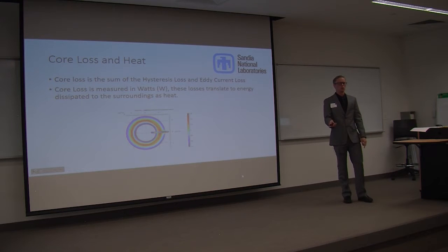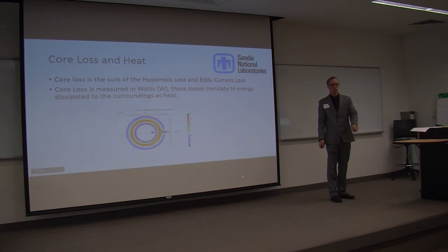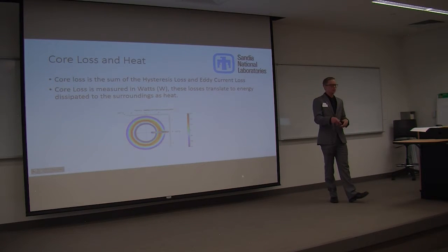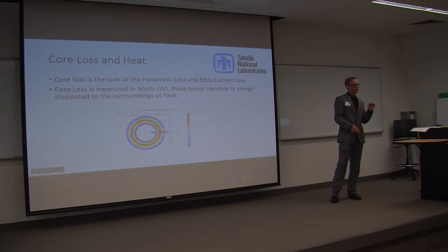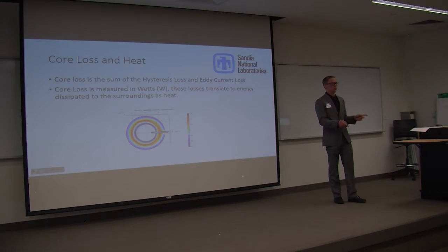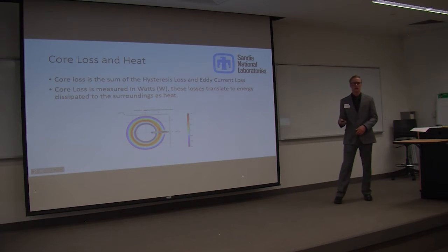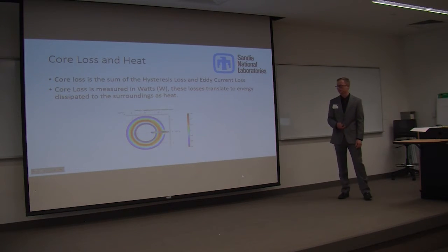So when current is positive and it's flowing one way, the magnetic little subdomains, or whatever you'd like to call them, are going to align with the current. But the moment the current switches and reverses because of this AC current, they'll flip around and flip the other way. And it's almost instantaneous, but not all of these little domains flip. So we have a couple of these domains that are straggling, and they need more energy to get flipped. And this causes the core loss. So it causes more work to basically flip, and this work then has to be turned into some energy that's just dissipated as heat, which we can't measure in the lab. We can measure all the physical properties, but we can't measure heat.